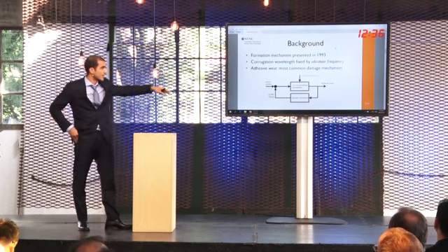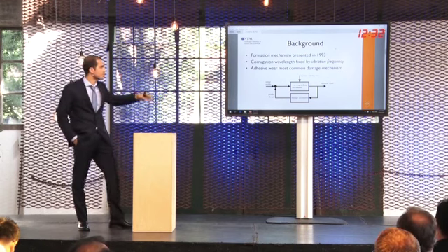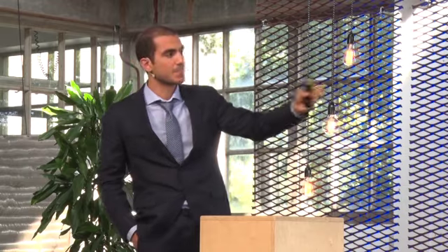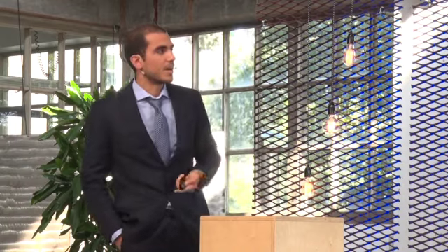All right, so formation. Here we can look very quickly at the formation mechanism for corrugation, which is composed of two components, a wavelength fixing mechanism and a damage mechanism. The wavelength fixing mechanism relates the wavelength of corrugation with the frequency of vibration of the system, while the damage mechanism is the way the material is removed by the system.